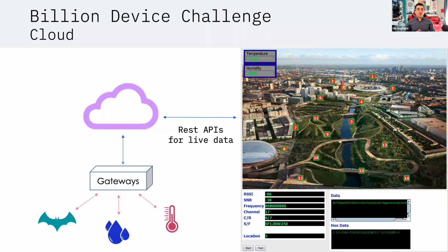Because sometimes when there were fans traveling to the stadium in the park, we couldn't use Wi-Fi anymore, because all their devices were occupying the 2.4 gigahertz band, and we had to move on to another band, which gave us the opportunity to go into LoRa to send and receive data. But obviously LoRa was only good for low throughput data, so we had to only send metadata at that instance. At other times, we could easily route data through another device, which could have had better communication or lower SNR, as we call it.